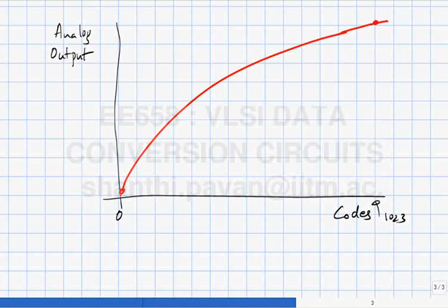how do you, the first thing is to find the DNL and the INL, the first thing is to find the LSB size, right. So, what do you think I should do? I mean, clearly it doesn't make sense to use, within quotes, the nominal value: when you buy a DAC, the manufacturer will say that the nominal LSB size is likely to be so much. But even if there is a small deviation in the LSB size, you can see that, for example,